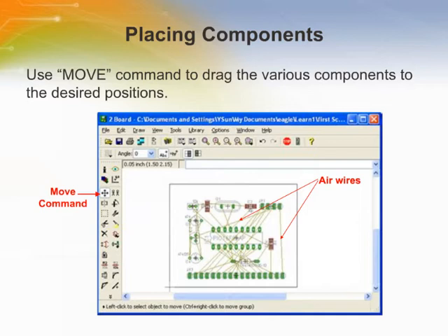All the signals you created in the schematic are currently called airwires, thin yellow lines that are drawn in the shortest possible way, crossing each other as needed. They stay connected to the component pins even when you move the component around.